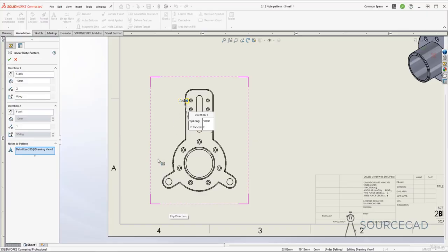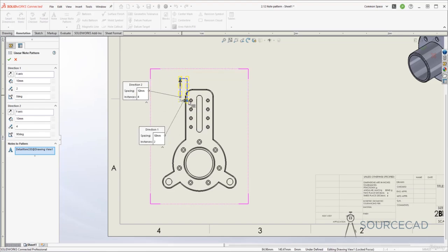Now let's select number of rows and columns. So here number of columns is 2, that's along X axis, along this one, which is right. Along Y axis we need to make it 4. So I'll type 4 and tab key and done. But we have a problem. This is going up, it should go down.